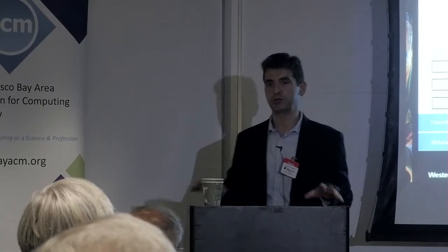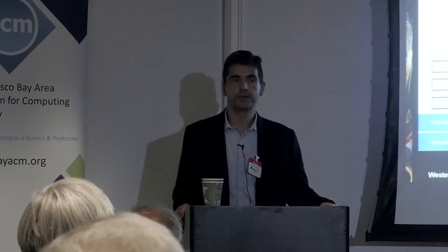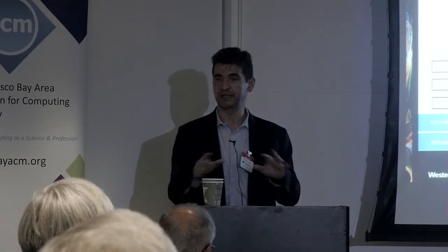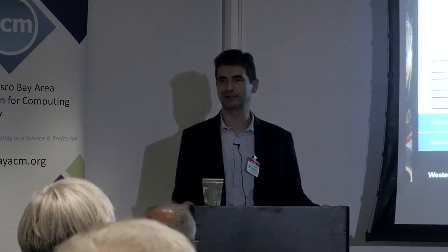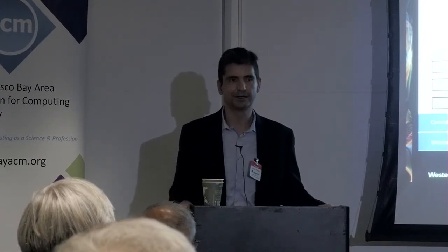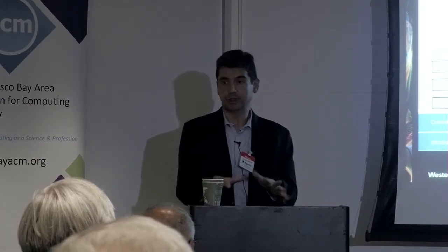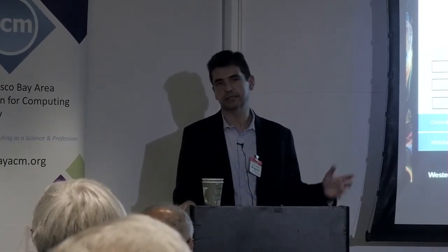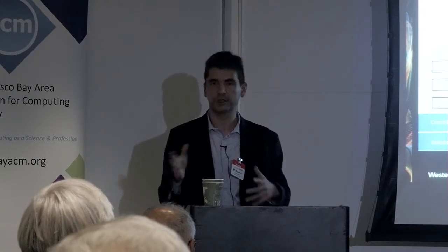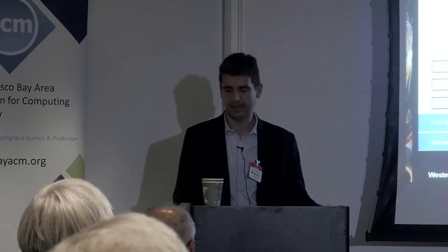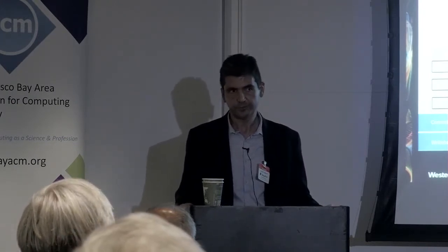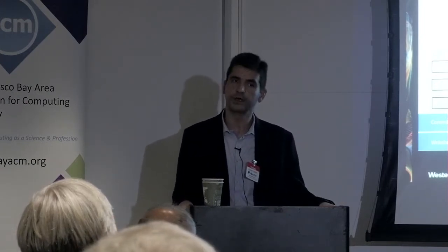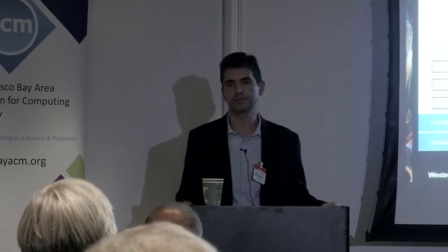If you have 2 execution pipes, and if you have perfectly random generated code where the instructions are not correlated to each other, not hitting the same registers, etc., you can kind of get a double acceleration. But that's not really realistic. Realistically, when you have code, the same registers will be referenced, and what you can realistically accomplish with a dual pipeline and a two-way issue core is about 25% acceleration.